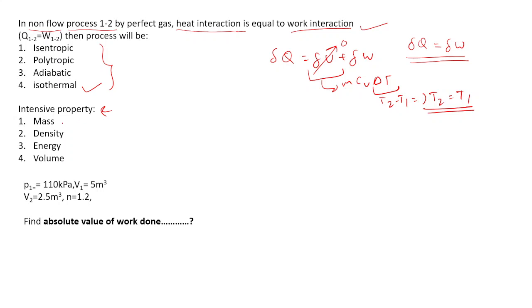Here, first, is mass intensive or not? Not, sir, it is density. Only density, right? For this type of intensive and extensive problem, keep in mind that the ratio of two extensive properties is also an intensive property. Anywhere it comes, the ratio of two extensive properties is intensive. So just quickly this problem.